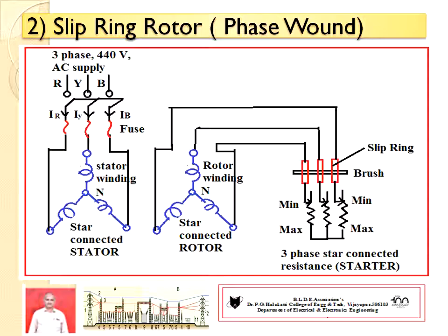After the starting of the motor, we have to go on decreasing the value of resistance. The corresponding speed of the motor increases. Hence, if you bring this resistance to minimum position or zero position, at this condition the motor attains its rated value. Hence, the motor reaches its rated speed. Hence, this external resistance circuit is also used to control the speed.